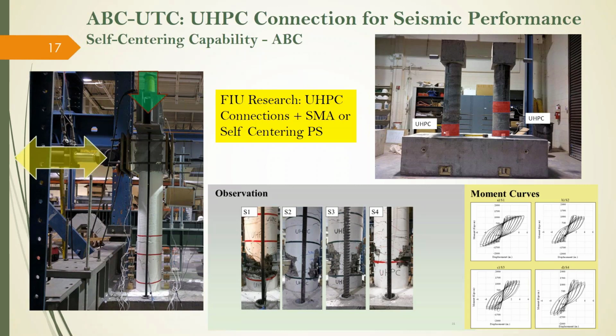So what we are considering is using the shape memory alloy within that plastic hinging zone to bring the self-centering and seismic resiliency. So these both have been tested in different places, for different reasons, and a bridge is built with shape memory alloy. So this is the next step that we are looking forward to.